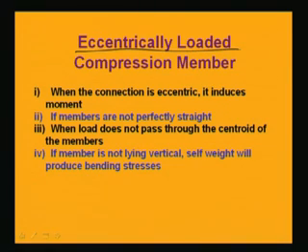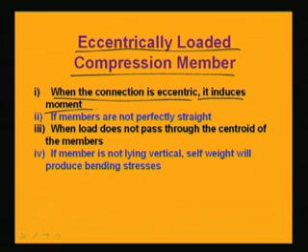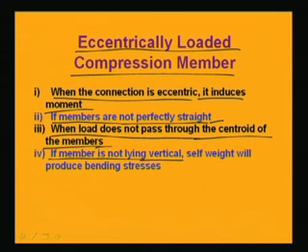Now we will go with the eccentrically loaded compression member. Generally when the connection is eccentric, it induces moment as we know, and if members are not perfectly straight, then also this type of situation will arise. Again, when load does not pass through the centroid of the member, then also chances of eccentricity will be there. Again, if the member is not lying vertical, self weight will produce bending stresses.